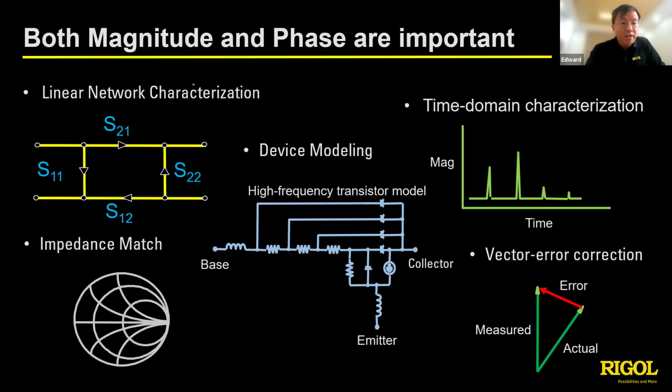So S21 means the first port transmits signals to the device under test, and we get the transmitted signals by the S parameters here. So the 1 to 2, that means S21, from port 1 transmitted to port 2. Okay, so we can get the loss information, right?